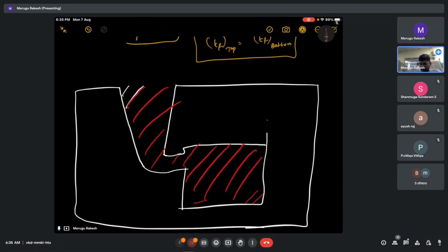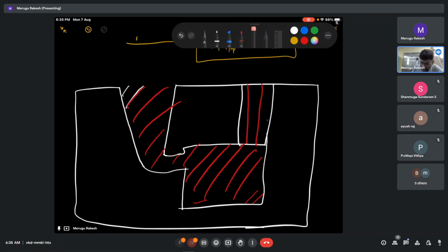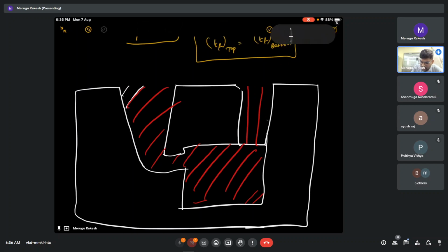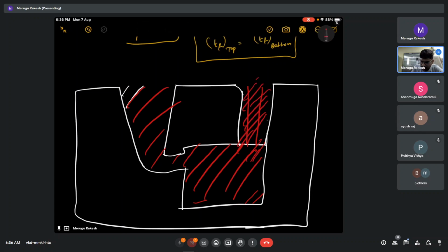We already discussed the shrinkage and the reasons for the shrinkage. We will also be discussing it in this session. To compensate the shrinkage, the pattern that we use will compensate only for the solidification shrinkage. But for the liquid shrinkage, we have to use a riser. Basically, we just connect the other end to the top of the casting. It's not simply connected; there are some design considerations that will be taken before doing this.